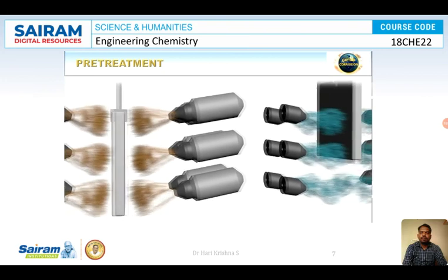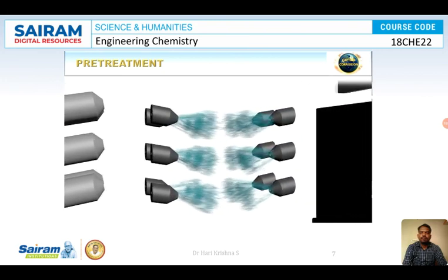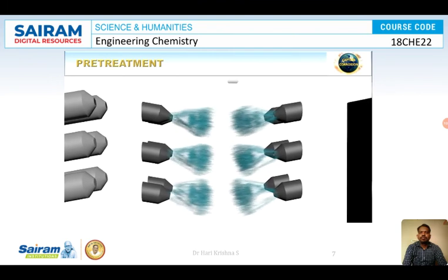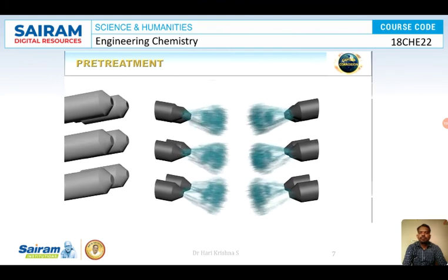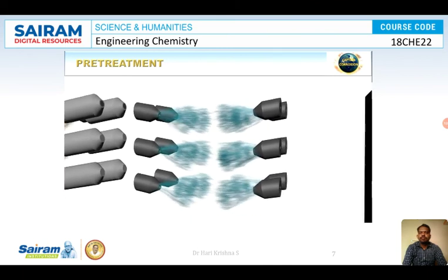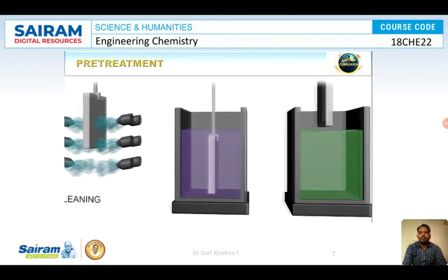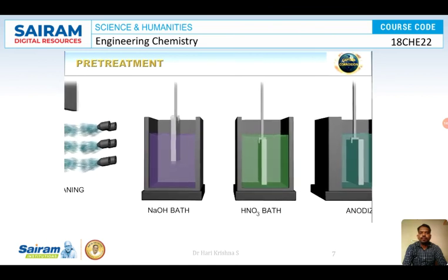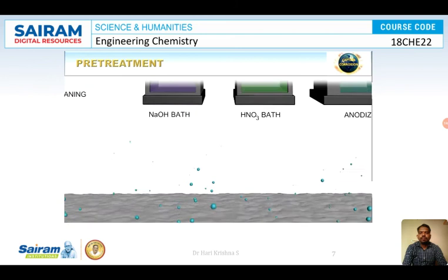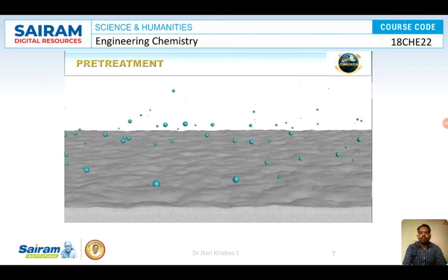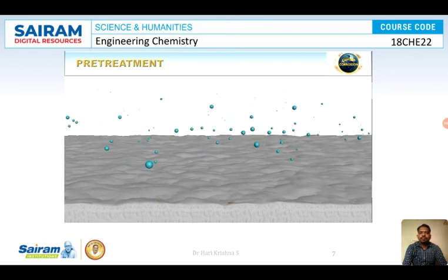Then the metal substrate is cleaned from loose particles and minor impurities by rinsing with deionized water and organic solvents. In the next stages, the aluminium substrate is treated with warm sodium hydroxide and nitric acid in order to chemically remove the top layer of the metal, which results in a very clean surface and also exposes near-surface intermetallic particles.